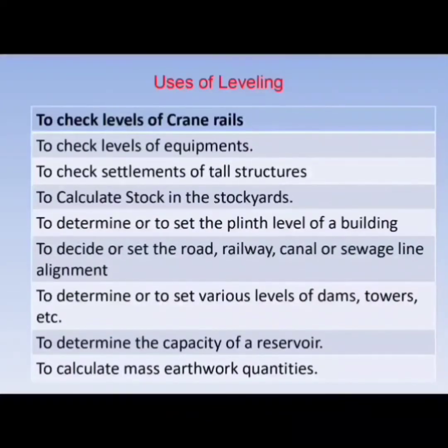Uses of leveling: to check the levels of crane rails, to check levels of equipment, to check settlement of tall structures, to calculate stock in the stockyard of raw materials, to determine or to set plinth level of a building, to decide or set the road, railway, canal or sewer line alignment, to determine or to set various levels of dams, towers, etc., to determine the capacity of a reservoir, to calculate mass earthwork quantities.